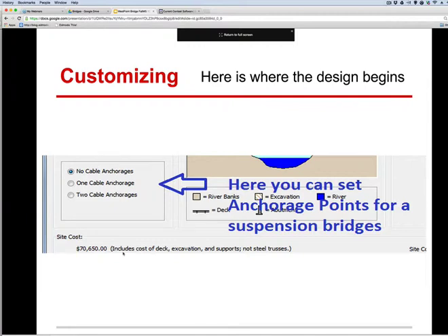A lot of time you'll see in different science competitions, build something to hold the greatest amount of weight, and it has to be the lightest possible. Well, you're measuring efficiency, but in the real world of engineering, they don't do that. What they do say is, hey, this needs to hold this much weight. We want a factor of safety of 1.5 or 2. So in other words, we tell everybody the bridge can hold 10,000 pounds. In reality, it can hold 20,000 because it's got a factor of safety of 2. We make it twice as strong as we think we need it to be.